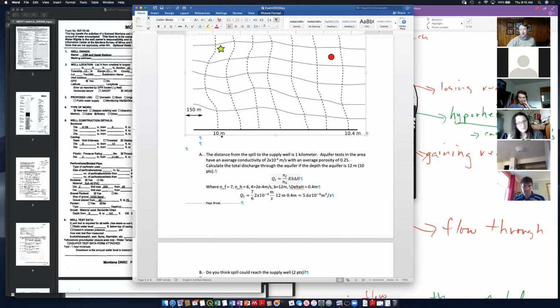You can think about it this way. My first head drop is this first contour. So everyone counted the number of contours. Well, not everyone, but a lot of people. It is the number of head drops. So you start at 0, 1, 2, 3, 4, 5, 6.